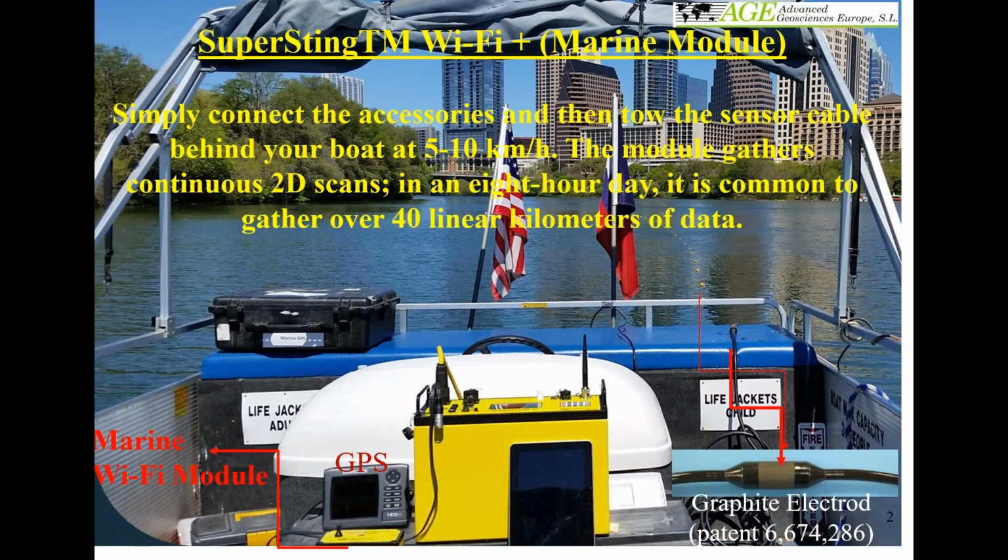When the same instrument is used for land studies or stationary studies, you need to change back to the land firmware. For the new generation SuperSting Wi-Fi, you just need to add what we call the marine module.